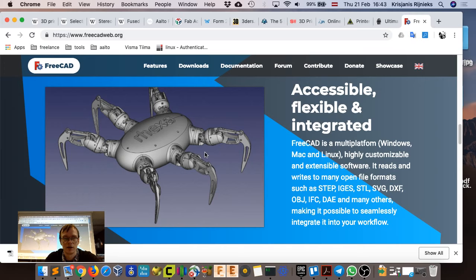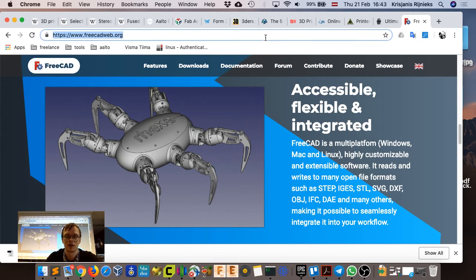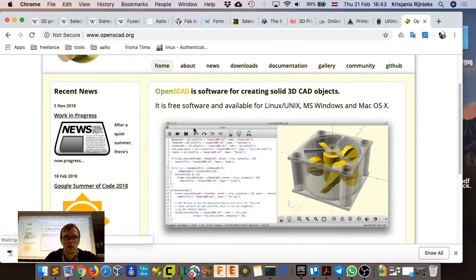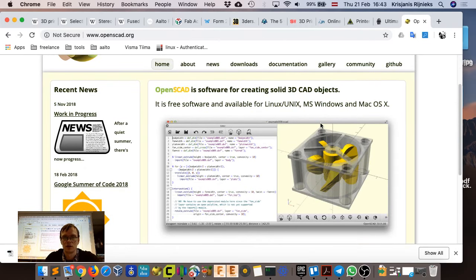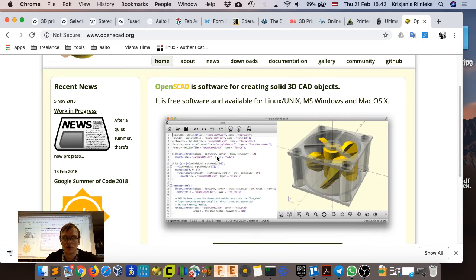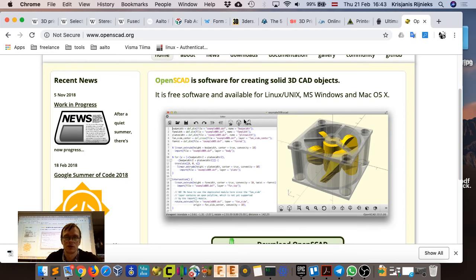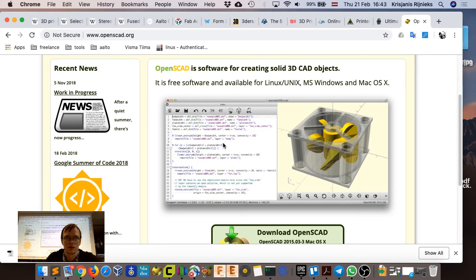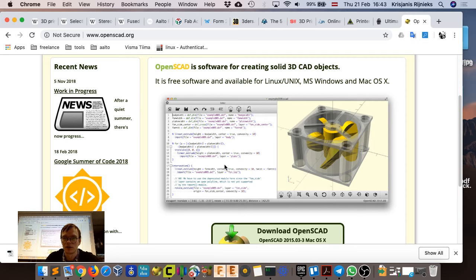But it looks like a nice option, and it integrates very well with the software called OpenSCAD, which is more of a what you write is what you get interface, where on one side of the interface you write code. So this is a tool where you actually write code in order to get your design. You can make variables in order to make your design parametric. You can make functions. You can separate the design in multiple files.